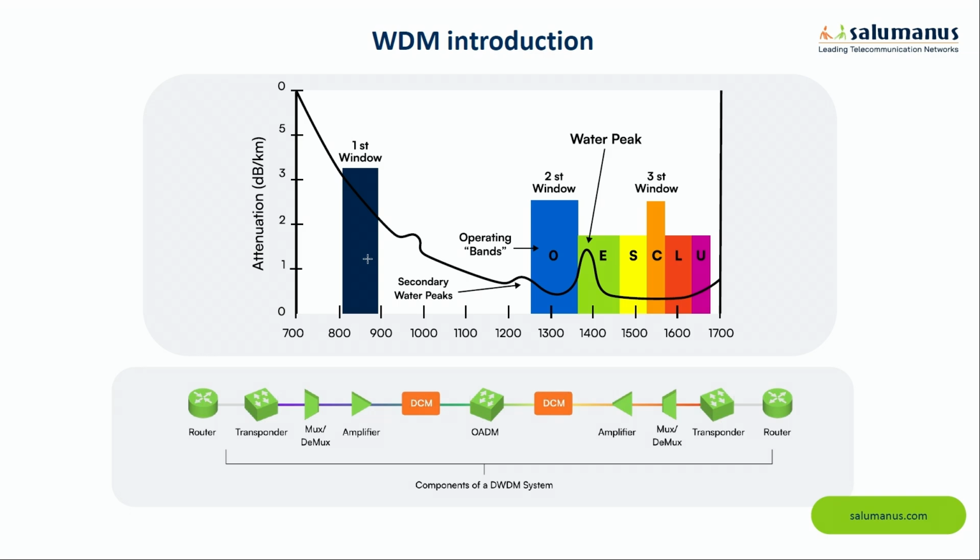But now, because operators are running out of frequency, as we need to put more and more data, they are looking at two narrower bands, S band and L band. But this is what is happening for the very long distances. We also need to keep the short distances connected, and this is where the O band becomes a bit more popular, especially when we're talking about 100G connectivity, which is probably the most popular connectivity among this society here. We don't need 400G or 800G yet, or only very rarely, but 100G could be a very good solution for that.